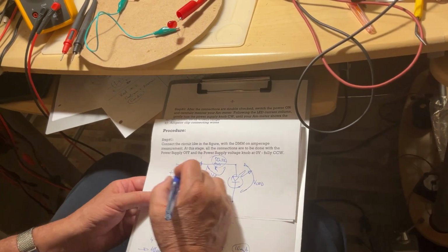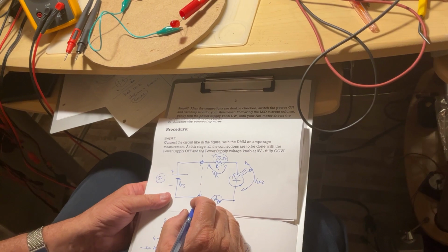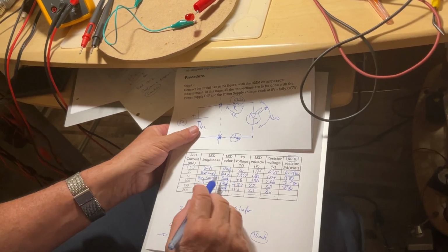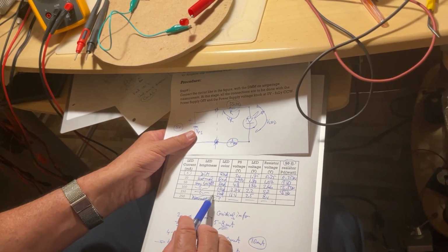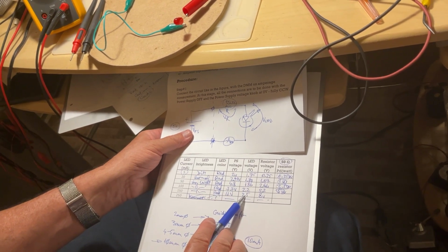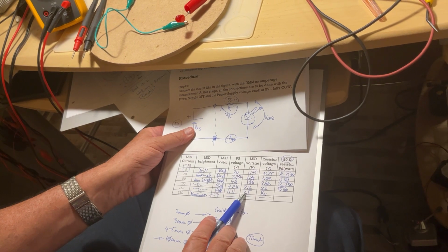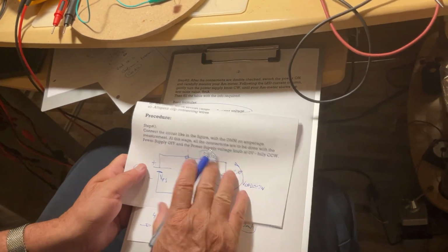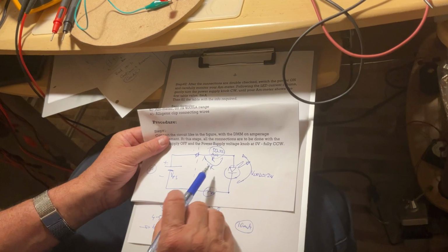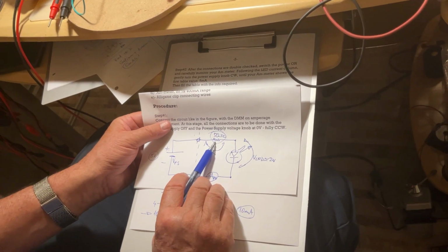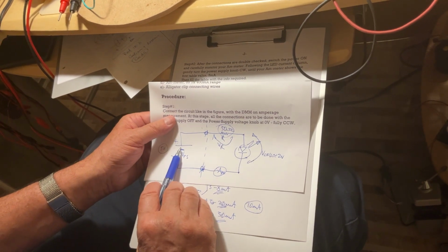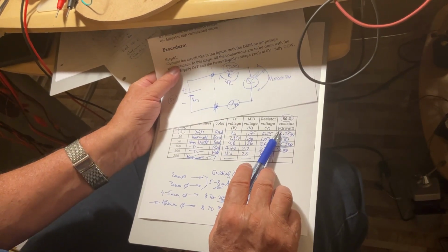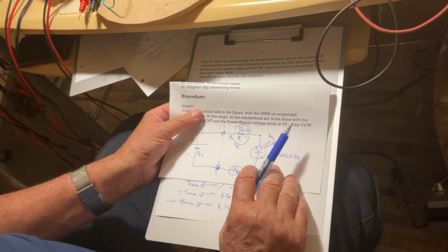And if you connect here 5 volts for the power supply, and you know the voltage across the LED, as the voltage went bigger and bigger from the power supply, the voltage was not exactly maintained identical across the LED. But let's say from the first to the last value, if we calculate the average, it is somewhere around 2 volts. So the voltage across the LED remains around 2 volts. Where is the rest of the voltage dropping? Across that resistor. This is the one absorbing the difference in voltage between the power supply and the LED. This is why it's called the dissipating resistor or the current limiting resistor, because it limits the maximum amperage passing through the diode.